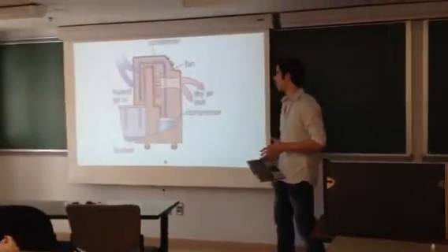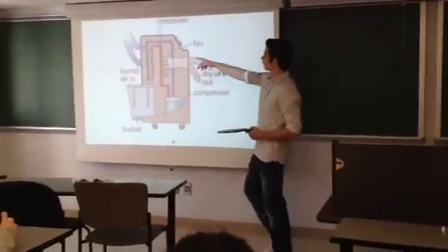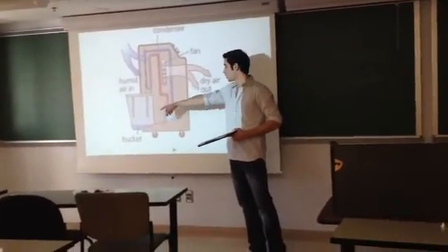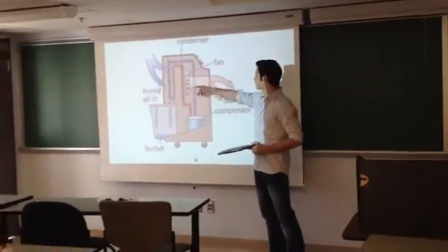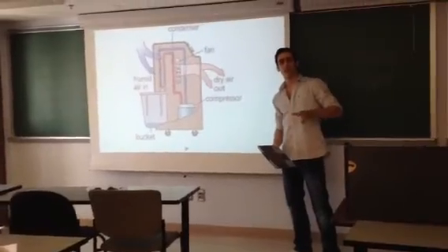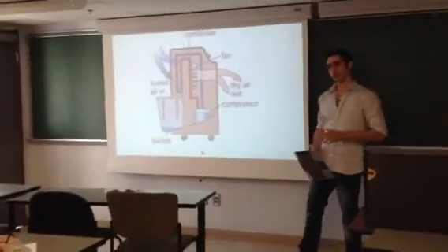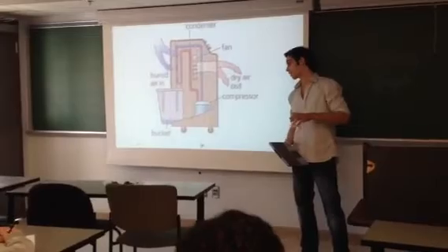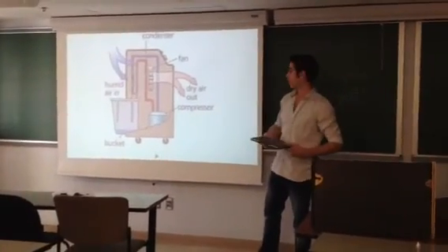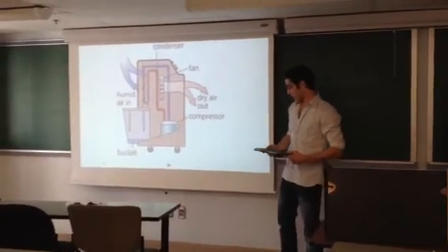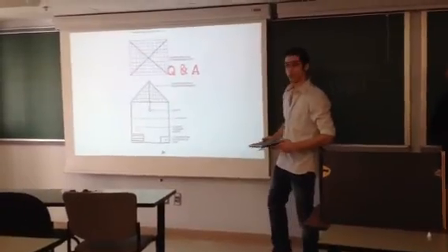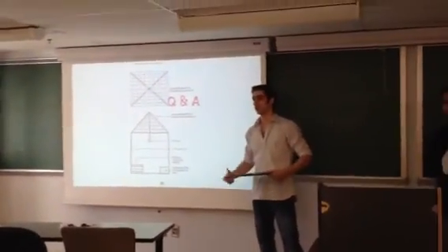functioning of the dehumidifier. The dehumidifier basically sucks in the humid air, condenses the water vapor in it into liquid water, which is collected in a separable bucket, and then the dry air is pushed out the other side. By doing this, the dehumidifier reduces the amount of humidity, and therefore reduces the negative effects that humidity has, and therefore provides a more suitable living environment inside the shelter. Okay, so this basically wraps up our presentation. Now we'll take questions. We'll be glad to answer.